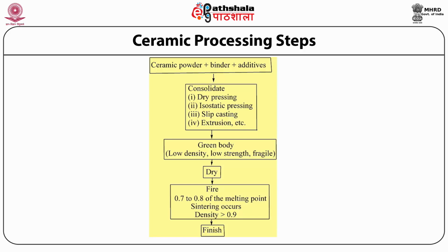In dry pressed articles, the moisture content is very low, but in products made using slip casting or other techniques which start with a slurry or paste, the moisture content is very high. A drying step is used in the latter case to remove the moisture.